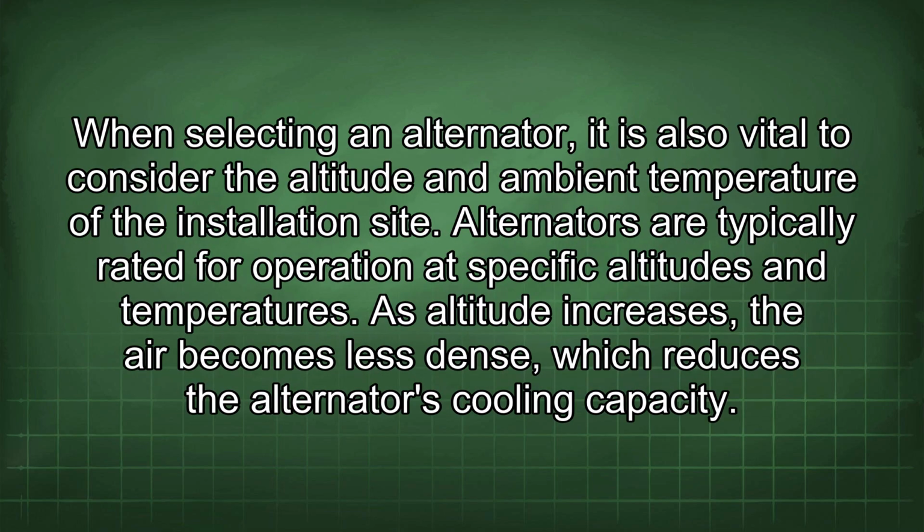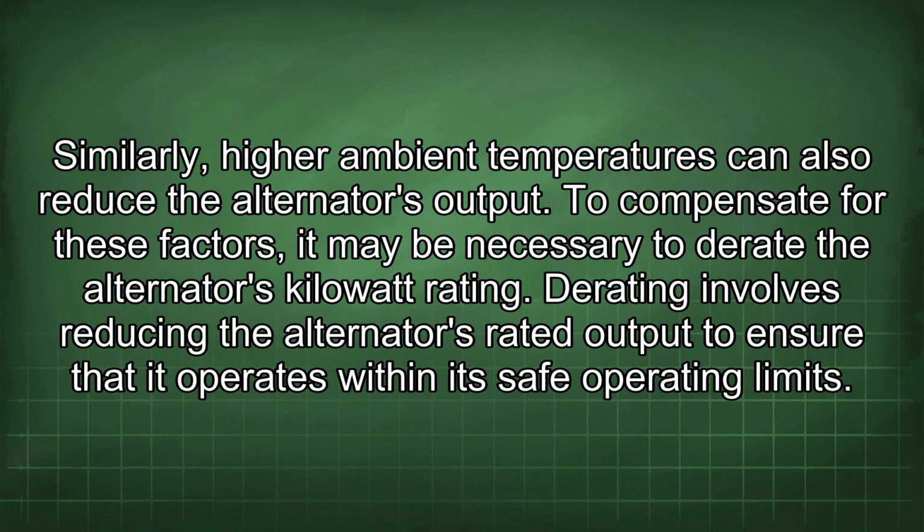When selecting an alternator, it is also vital to consider the altitude and ambient temperature of the installation site. Alternators are typically rated for operation at specific altitudes and temperatures. As altitude increases, the air becomes less dense, which reduces the alternator's cooling capacity. Similarly, higher ambient temperatures can also reduce the alternator's output. To compensate for these factors, it may be necessary to derate the alternator's kilowatt rating.